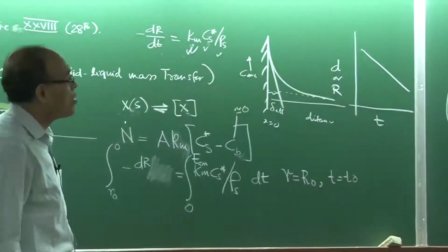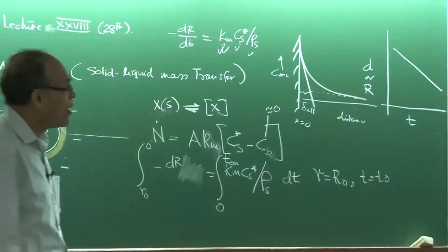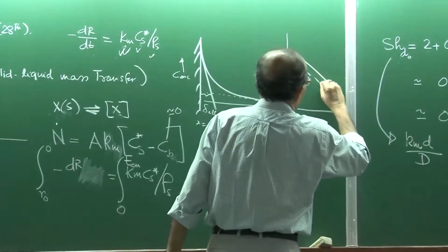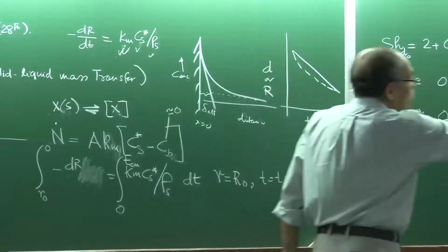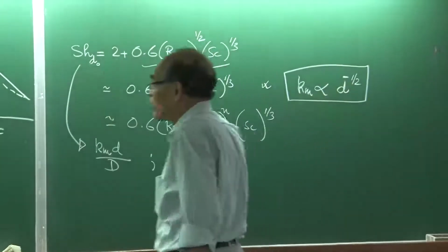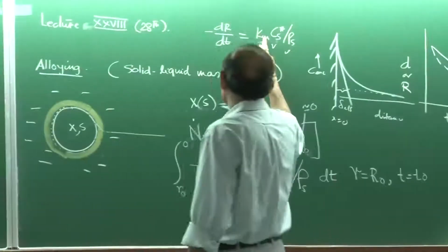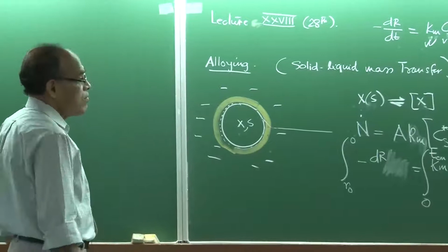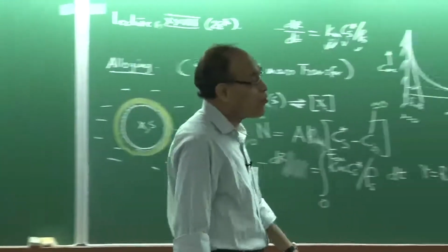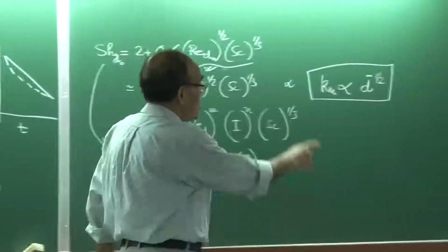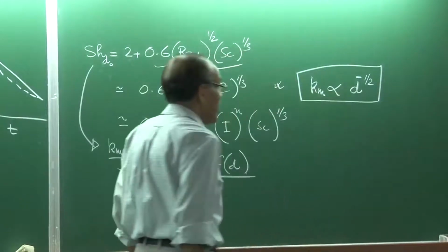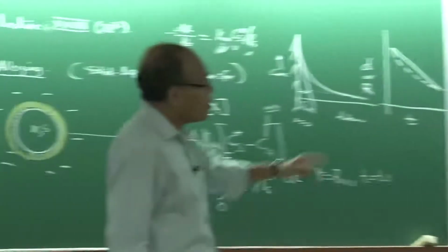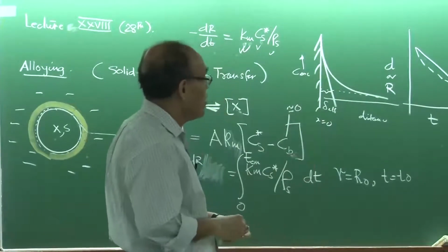Instantaneous radius or diameter will change as a function of time in a linear way, but the actual graph is going to be not linear, because Km is not constant but changes as the diameter changes, okay? And as the diameter becomes smaller and smaller, the mass transfer rates become higher, and the mass transfer coefficient becomes higher and higher. You can analyze this problem.